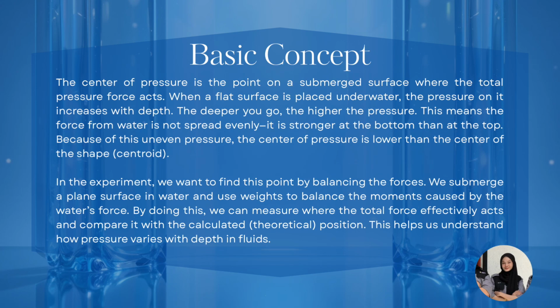The center of pressure is the point on a submerged surface where the total pressure force acts. When a flat surface is placed in water, the pressure on it increases with depth. The deeper you go, the higher the pressure. This means the force from water is not spread evenly. It is stronger at the bottom than at the top. Because of this uneven pressure, the center of pressure is lower than the center of the shape.